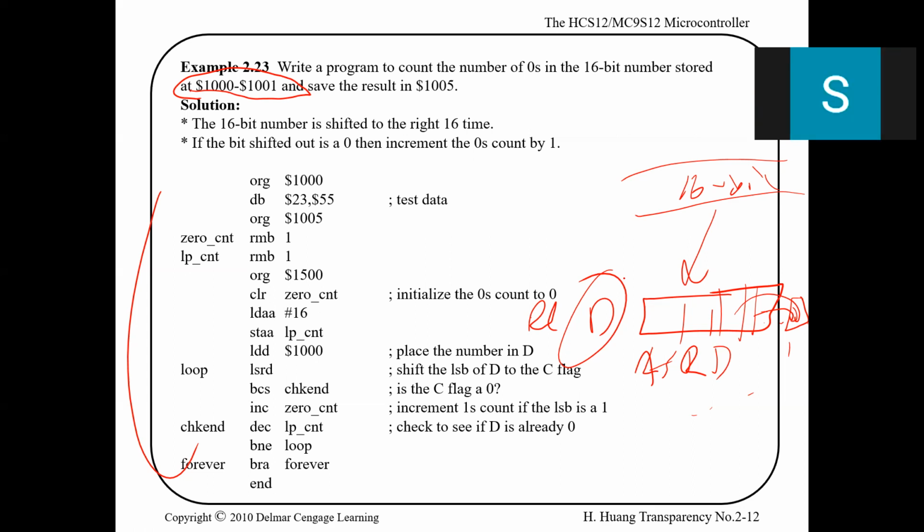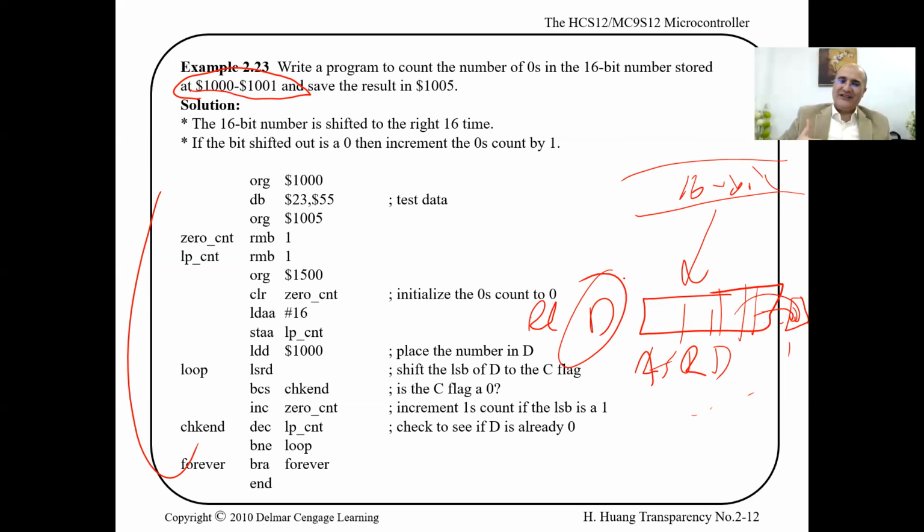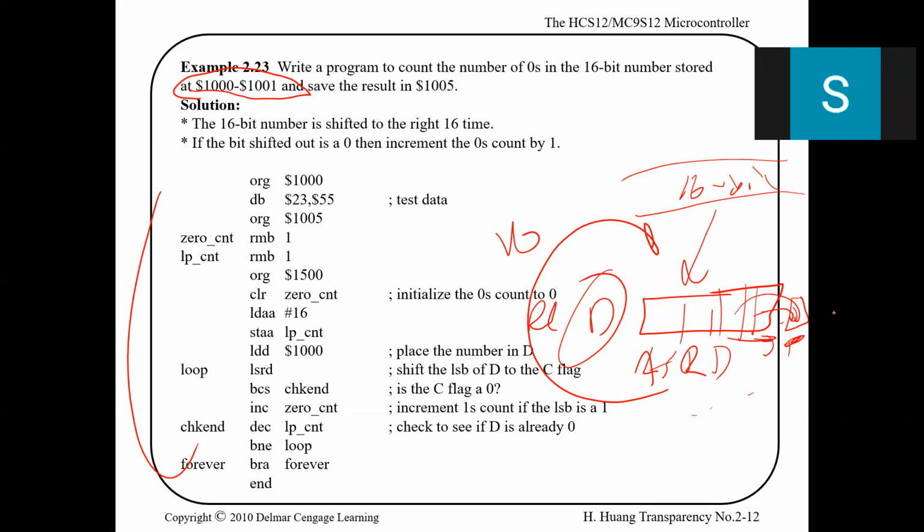In a loop, it's a single instruction. The number you're going to do an XOR with or an AND with is going to be different than the one you used before. So you're going to do something 16 times repeatedly. This rotate or shift thing, you can do one instruction repeated 16 times, right? Every time it's a shift. You check the carry flag. Okay.